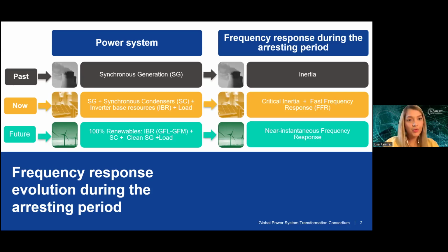In future, we are expecting 100% renewable systems. That means that we will have grid forming, grid following, and also synchronous condensers, clean synchronous generators, less than in the past, when all the system was driven by synchronous generators. And we also are including load to provide that kind of services during the frequency response during the resting period.